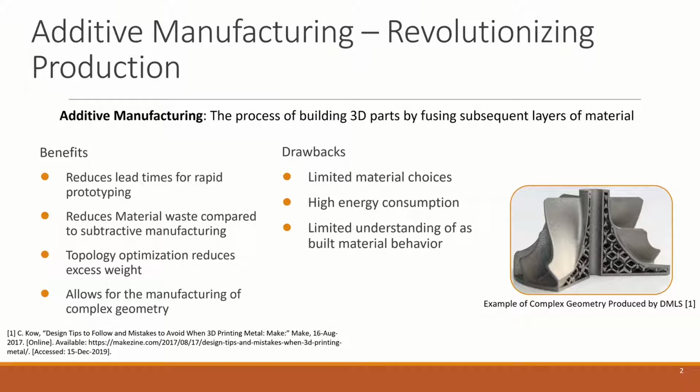It does not require a mold. There is minimal possibility of cold shuts, washes, and misruns. Additionally, there is likely less post-machining required for AM processes. The layering technique also allows for complex geometries which can lead to more weight-efficient parts.